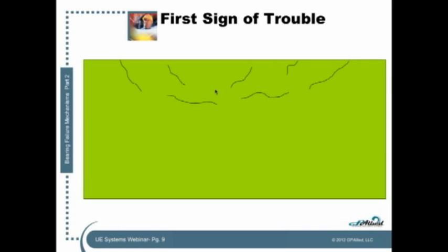This is how the bearing defect began. Now, this is why ultrasound works really well finding these early bearing faults, because as the roller passes over this spot, I get a little bit of relative movement inside each one of those cracks. As the stress cone from beneath the roller or bearing passes over that spot, I get a little movement from one side of the crack to the other.